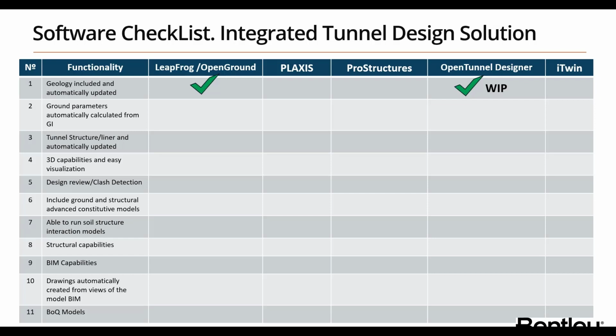At the same time, because you are creating named versions, you can export that new version to IFC. OpenTunnel will be able to read it and also update the model in OpenTunnel. And something that we are working on for future versions will be to automatically connect to Leapfrog through Central and read the geological model from there and update directly without the need of importing through IFC.